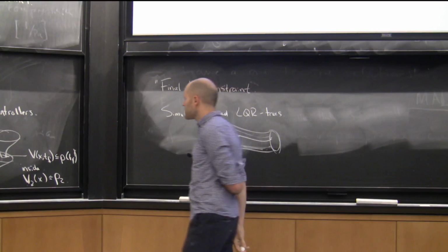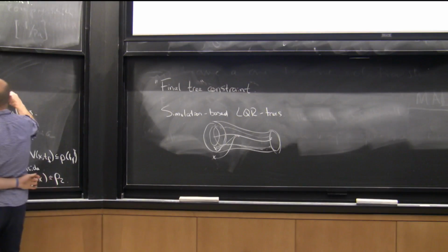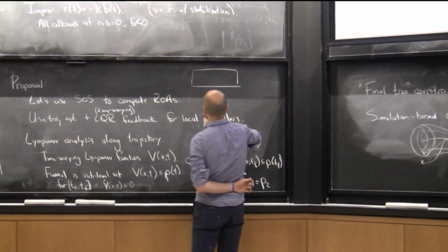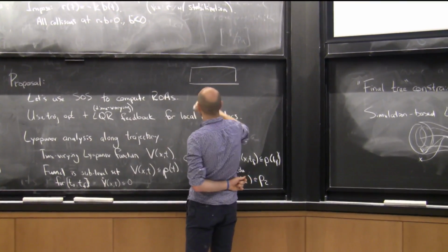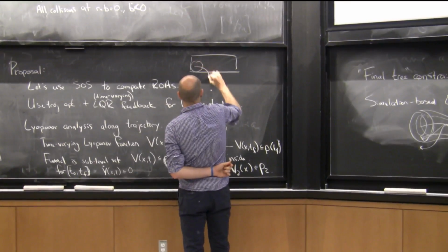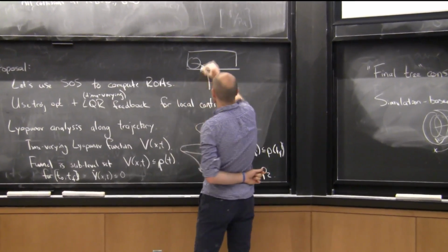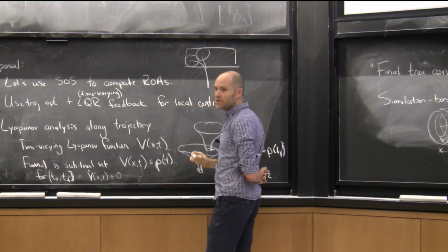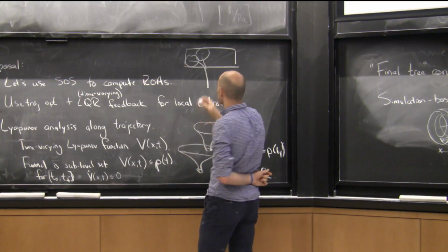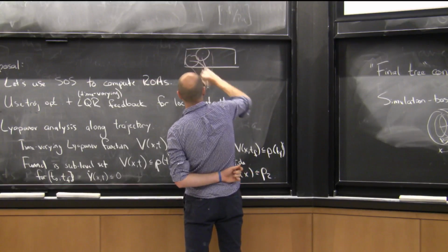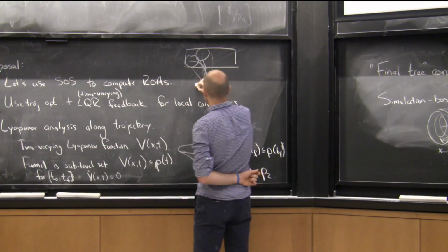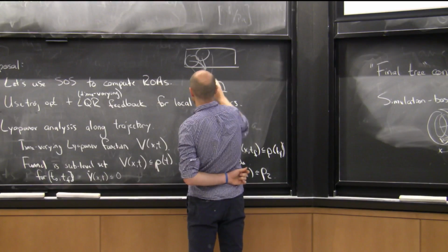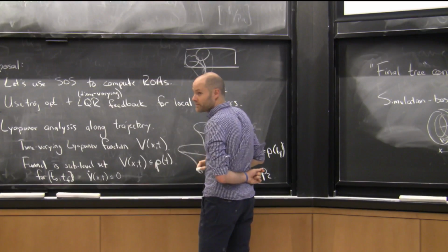So you would fill the space. In the simple case, let's say I have an initial condition that's fixed, and I'd like to end up with a set of trajectories that cover this space. So I've got one maneuver that gets me here. I sample again, I don't have anything, so I come up with the opposite version of the tree that gets here. Each of these are funnels all the way back. And then if you had a set of initial conditions, typically we just sample here too, but you could try to achieve coverage in both places.